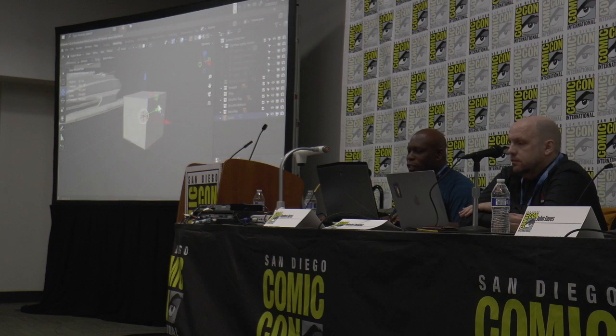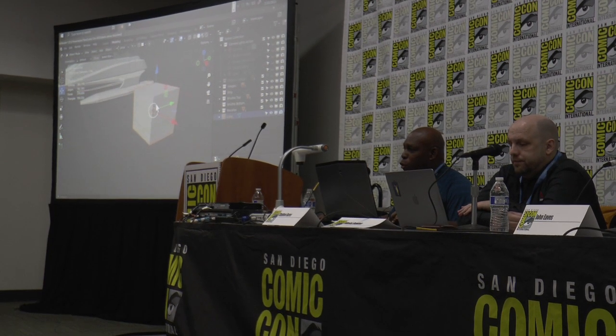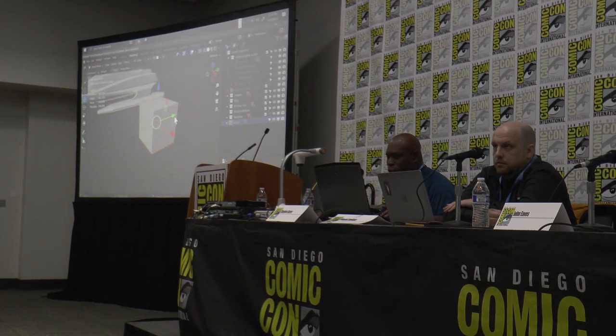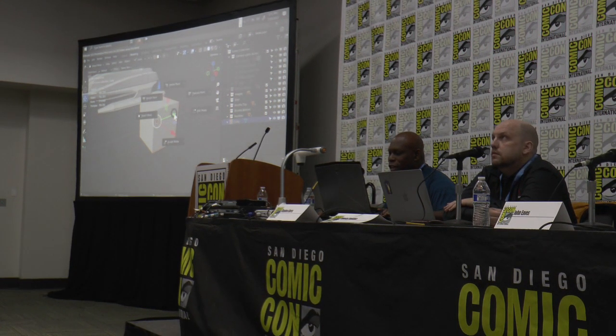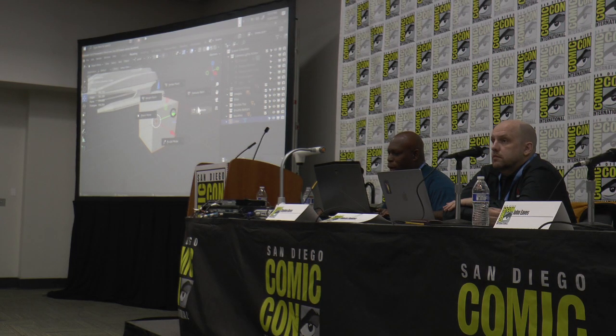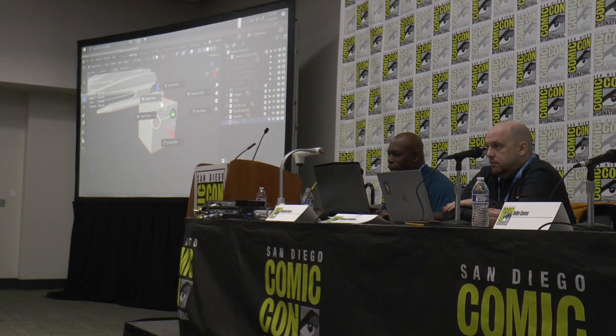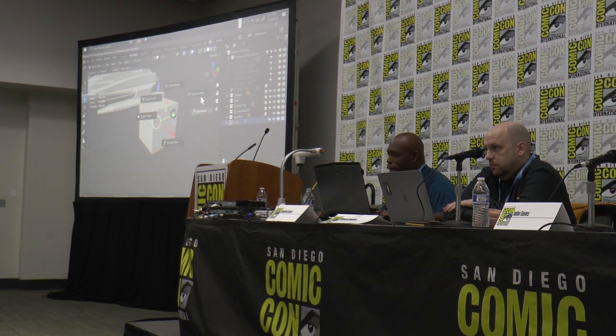Now, select it. I'm in object mode currently. That means I can animate that object. If I want to edit the object to create something different, I hit the Tab key to go to edit mode, and Tab again for object mode. And you have various other modes: sculpting mode, weight paint, and this one is for texture painting, if you want to paint on it. I'm interested in the edit mode.